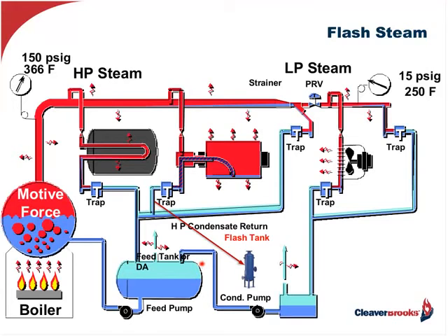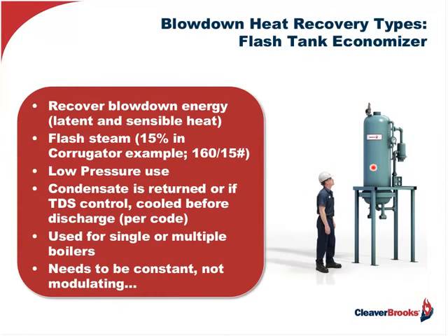Or we could take it to a storage tank. Any number of uses for that flash steam. Shell and tube heater, those BTUs can be captured in that way. And then the condensate that is left within the bottom of this tank can be used for boiler feed, or it could be used to preheat feed water. Any number of applications for that hot condensate that is left after the flash steam is captured.